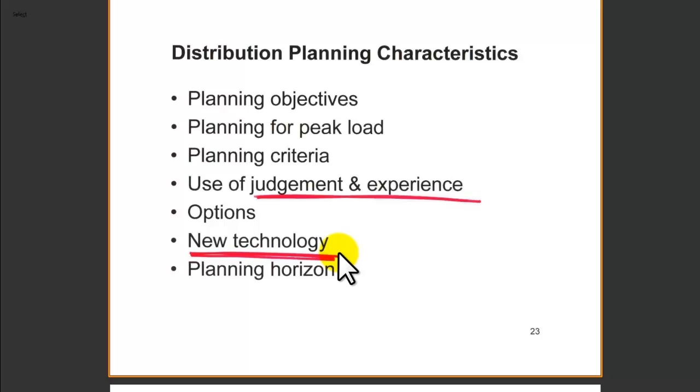These measure the system performance and the customer duration of power outage. A lot of the time they get the data inferred from the feeder head of the system, when the breaker trips or does not trip, and then a timestamp appears in the SCADA system. Those are the things they use to determine the reliability of the distribution network.